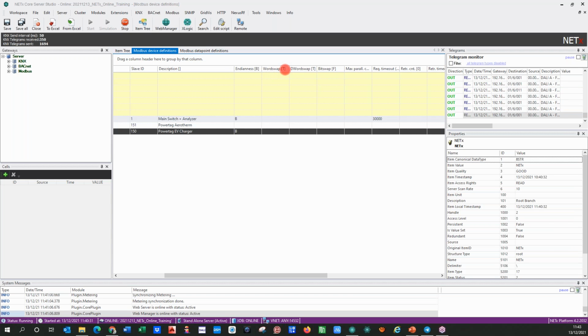Sometimes the info is not in the least weight byte, it's in the byte with the biggest weight. So we have to swap the bytes to get the information in the first, not in the last byte. So the word swap is for this, and the double word swap is the same when you have registers with not 2 bytes, but 4 bytes.